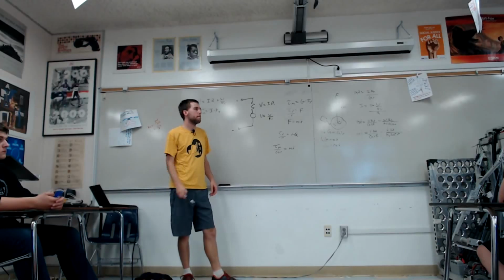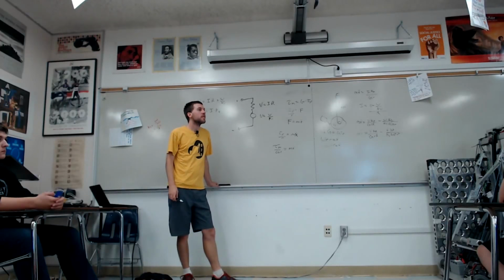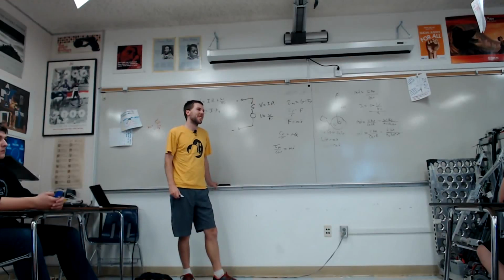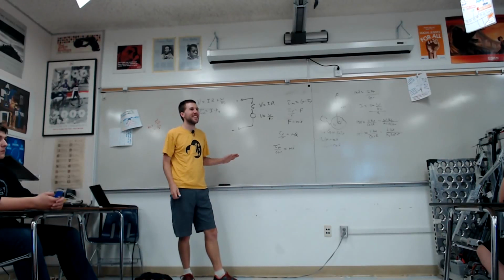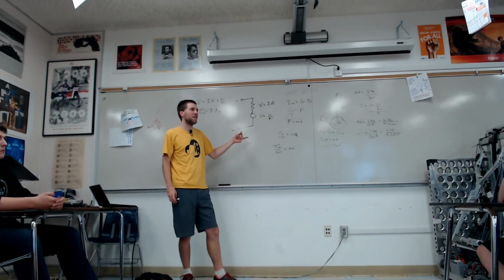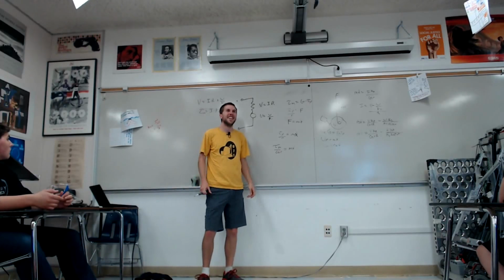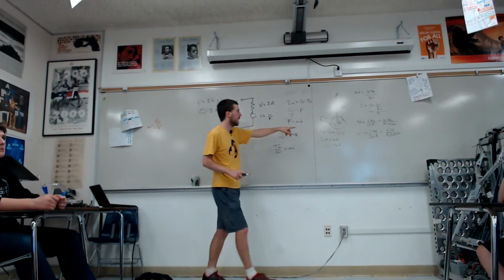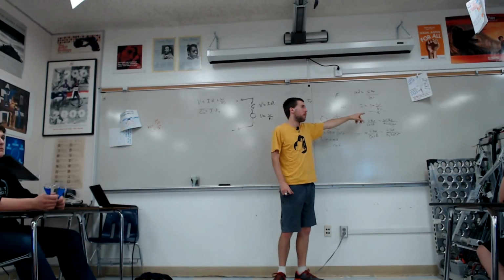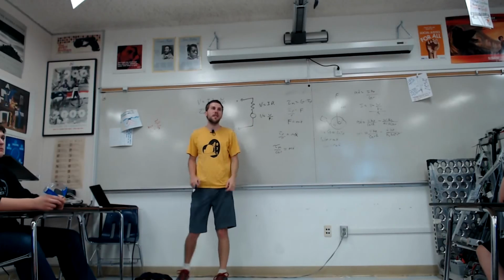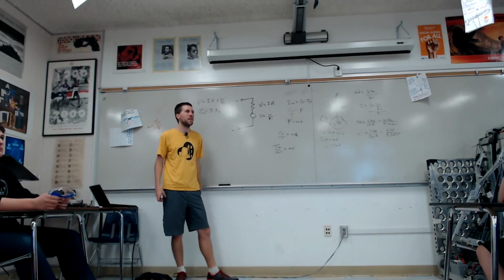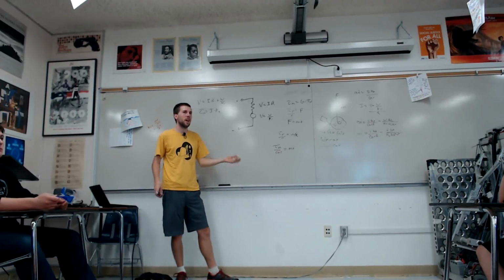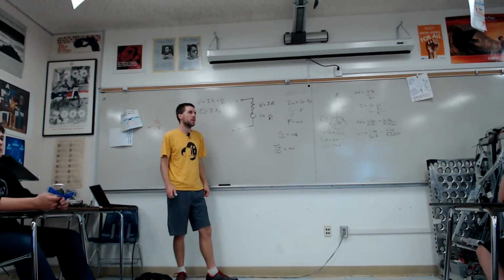Question: for your convention for G, are you trying to use the smaller G reduction, or 1 over it? 50-50, I pick a convention every year. As long as you're consistent, it doesn't matter. I probably picked a different convention for every robot, unfortunately. But I did try, so there are conventions for KV and KT out in industry, and I believe I've picked the correct convention from industry. They're just scalar constants, so you can invert them without anybody noticing in the math. So it's useful to be able to talk about them. You can always double check by looking at the units on those.